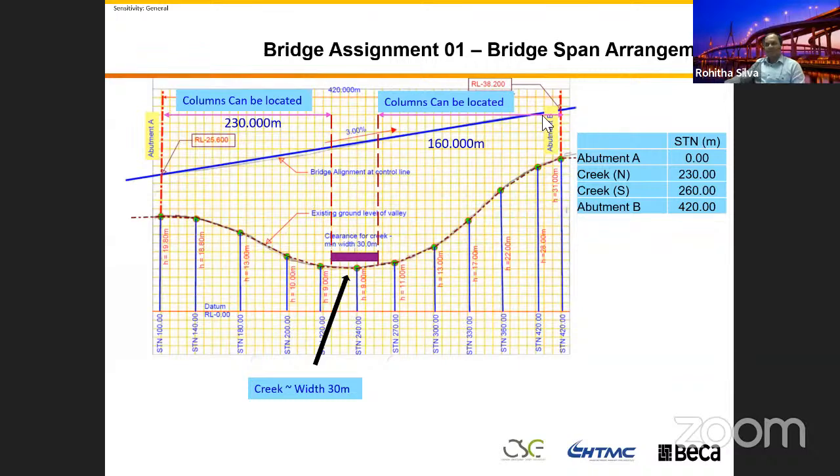If you have an option to fill this, it's much cheaper to fill here. A lot of excavated material, drilling, excavation and everything, right? You have to bring material to build the access road. You can reutilize that material to backfill this area if it is allowed.